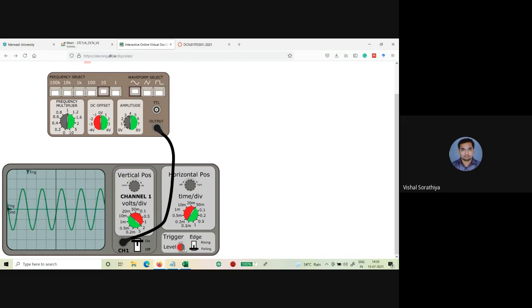Now, the display screen is only going to capture that signal whenever the triggering amplitude and frequency match the original, or the default frequency and triggering voltage set by your oscilloscope. So what I can explain through this: let's consider your triggering level, which you are making either up or down. Let's take that right now your triggering voltage is 5.